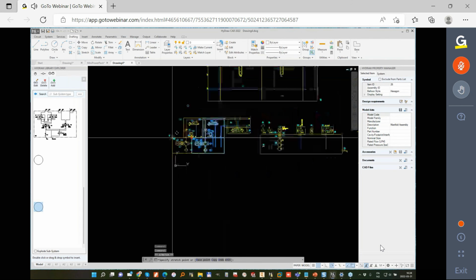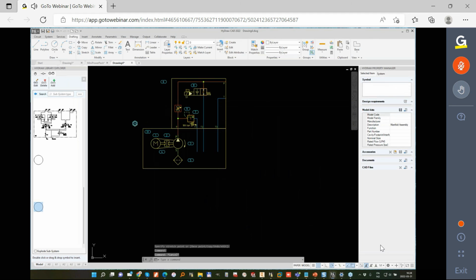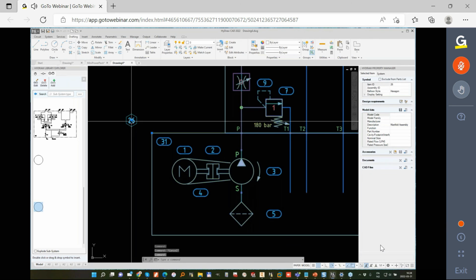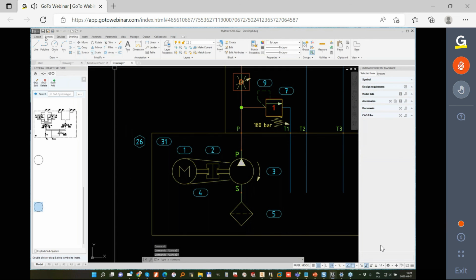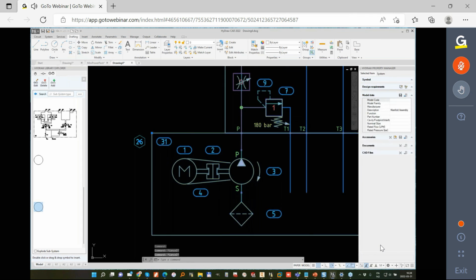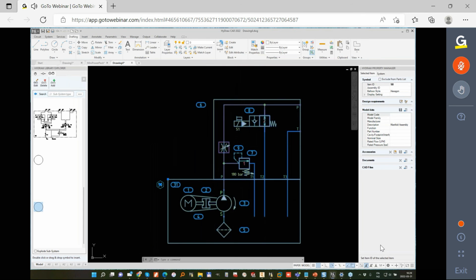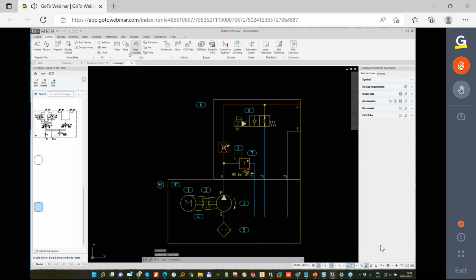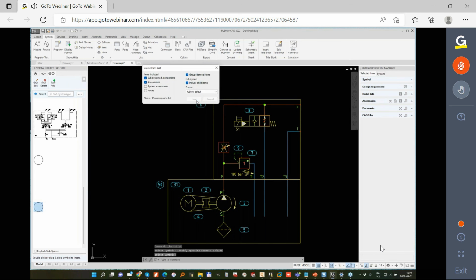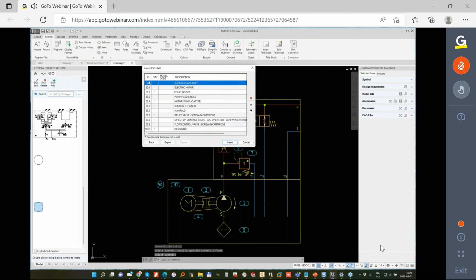This is our new subsystem. It works as a subsystem with an item number. And we can reassign the item IDs, and all the children will then follow with the item number. So if we create a part list for the subsystem, we can see that the item 50 that we have specified now is a prefix for all the symbols that were in the drawing.